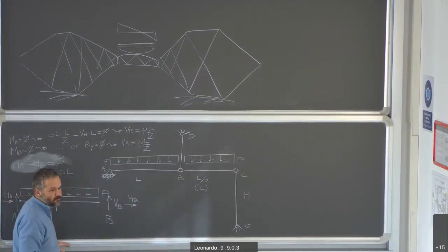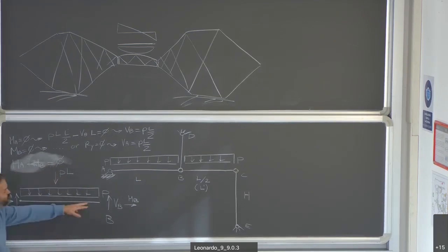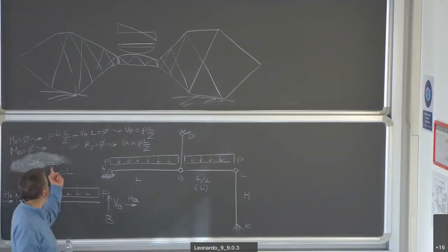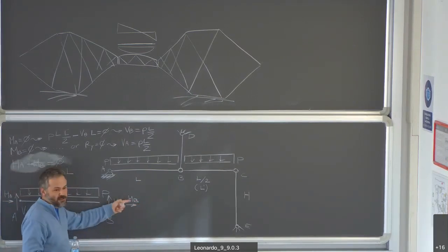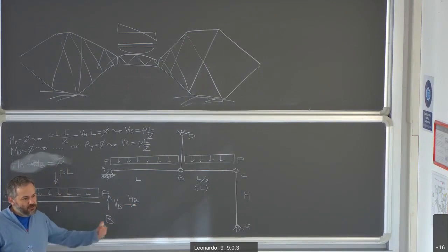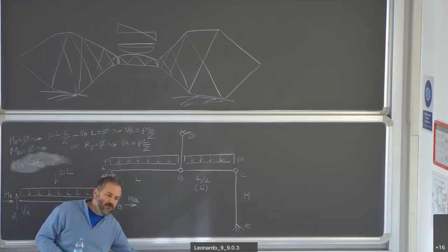Doesn't this equation tell us that they should be opposite in direction? Of course. Yes. This is the meaning. So HA equal to minus HB means I have to reverse this one, which is a basic condition. So the two should make themselves equilibrium. Or if you want HB equal to minus HA, so I reverse it and I call it HA. But then that's it. I cannot determine its value. The only thing I know about this axial force is that the two have to be equal in value, opposite in sign, but the value remains unknown. Have to work it out some other way.